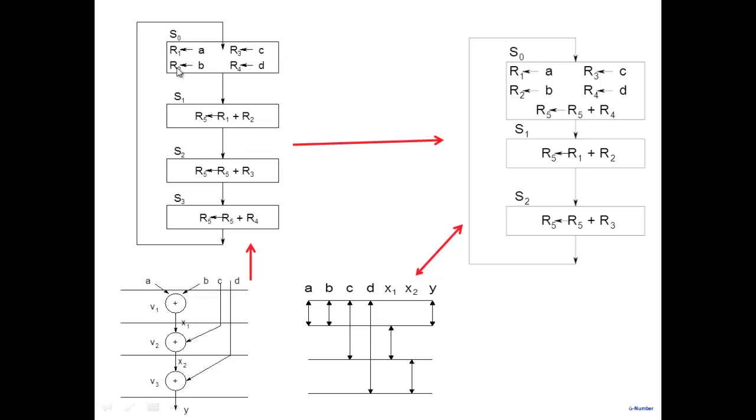So this is an intermediate ASM chart, which obviously nobody will really use, because it's wasting a clock cycle. It's simply you're reading it. So what one would normally do is take this and fold it back here, and then you don't waste a clock cycle.